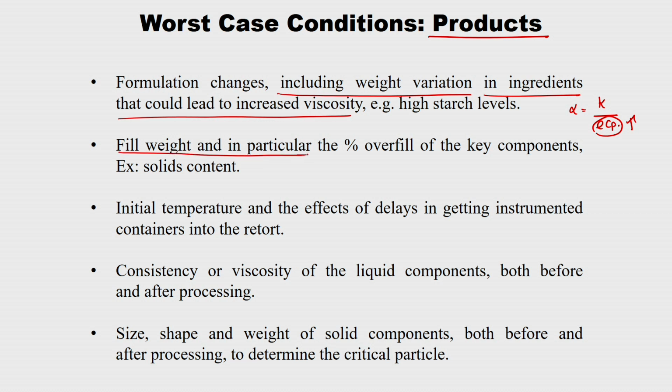And fill weight, and in particular the percentage overfill of the key components. For a particular can size, there is a particular amount to be filled. If you overfill, that also gives one of the worst case conditions. And initial temperature and the effects of delay in getting instrumented containers into the retort. This I have discussed.